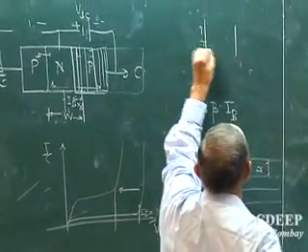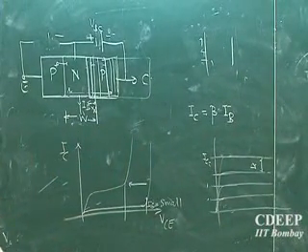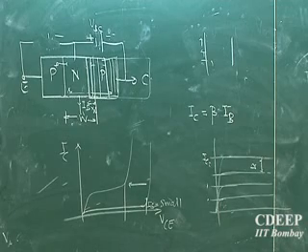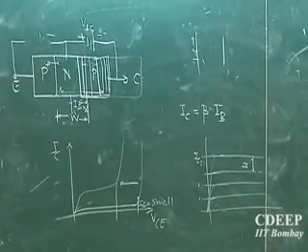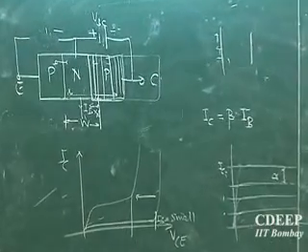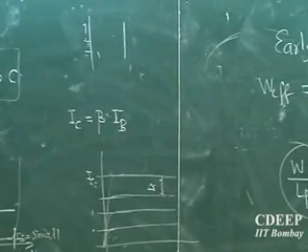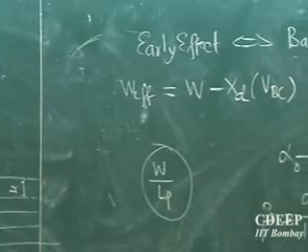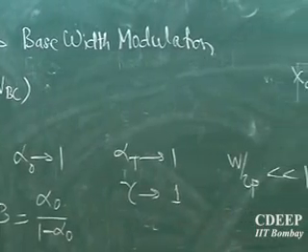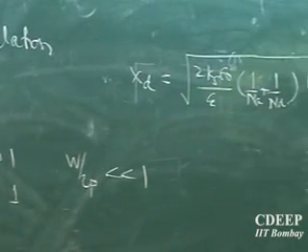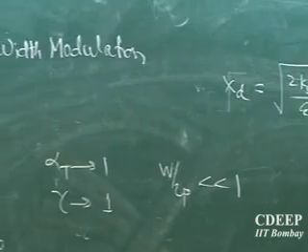If I have more holes entering the depletion layer, the avalanche multiplication will be quicker. Earlier it was only reverse leakage current, so fewer carriers, so they took longer to multiply. If you already have a large number of carriers entering the depletion layer and the field is higher, then they multiply faster, and therefore breakdown may occur. The larger the base carriers you create, the larger the number reaching the collector, the M number can reach earlier, and therefore avalanche may come earlier than the zero base current value.